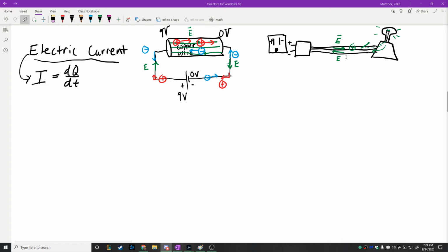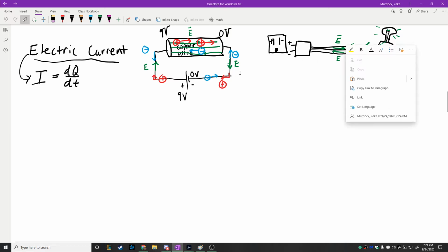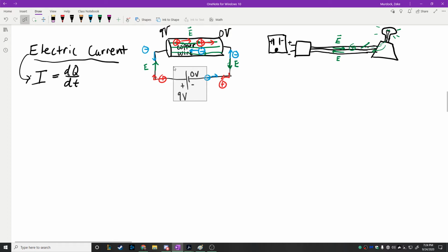You said this is a chemistry thing of why a battery has a limited life, because the charges were recycled. Wouldn't the battery work forever? No, it doesn't work forever, because as the battery operates, it develops corrosion and internal resistance that eventually makes it so that the terminal voltage is no longer 9 volts. So when you go buy a 9-volt battery, if you were to attach a voltmeter and measure its voltage, you often would not get 9 volts. And the older the battery is, the more that voltage drops. And at some point in time, the battery just isn't going to be able to work anymore.